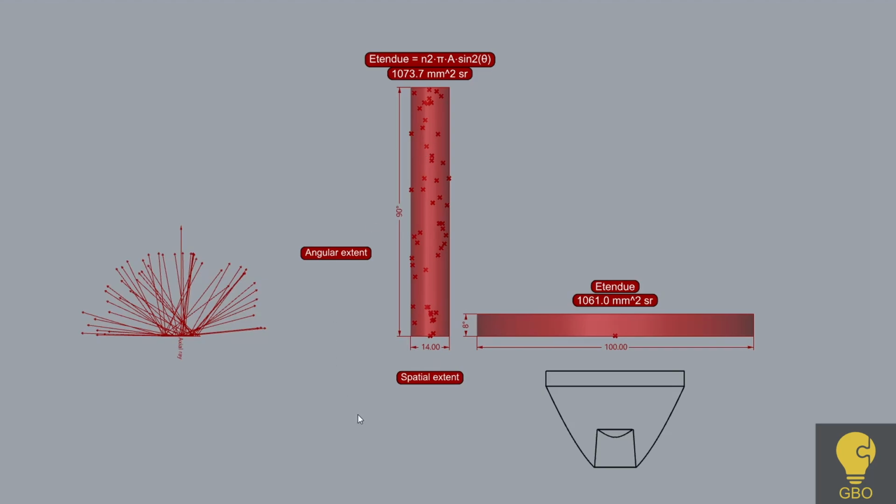So what's our takeaway from this long discussion? There is a hard physical limit, not a design limitation, a physical one, linking source size and beam angle for any given lens diameter. It is simply not possible to produce a very narrow beam from a relatively large LED using a relatively small lens, no matter how much time you throw at the optimization. So before you spend weeks or months trying to design your way around this limit, just don't. It's not a lens problem, it's the second law of thermodynamics.